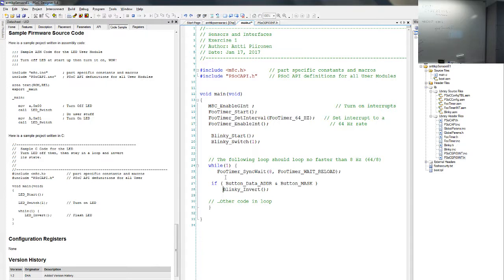And basically what this one does, as an input, the pin just checks if the voltage is higher or lower than, I think, 1 point some volts practically, but anyway, above 2 volts it's 1, and below 0.8 volts the state is 0. Okay, so if you are driving, for example, some LED directly, that might drop the output line lower than the level, although you are driving it.